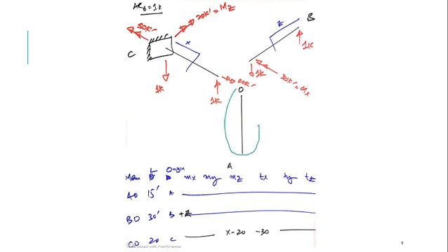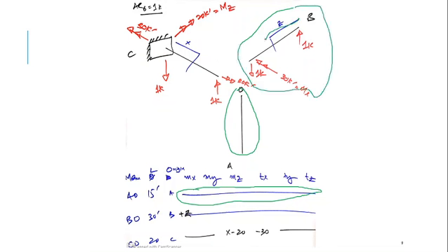This member is all empty, no activity here, so we have all zeros here. However, if you see this section, my origin is from here. I have to find all moments here. This 1 kip is forming an anti-clockwise moment here, 1 into Z. It should be balanced with a clockwise moment. Because this member is in Y, this load is in Y, and this member is in Z, this moment should be under the MX category. So here MX is equal to plus.